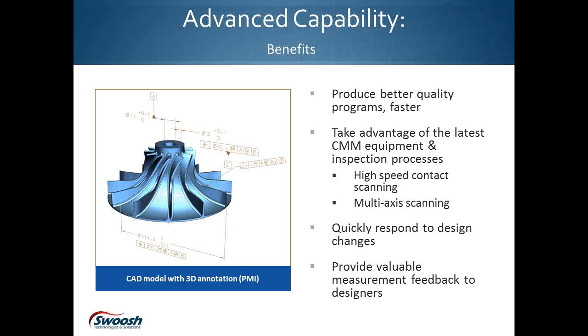So in NX CMM, we can program directly to design and manufacturing requirements. So we input 3D geometry based on a range of data translators. So we can import Parasolid, SolidWorks files, CATIA files, STEP files, whatever, you can do it. Okay, so whatever your customer's working with, NX can probably handle it. You can also program in the context of the CMM machine.